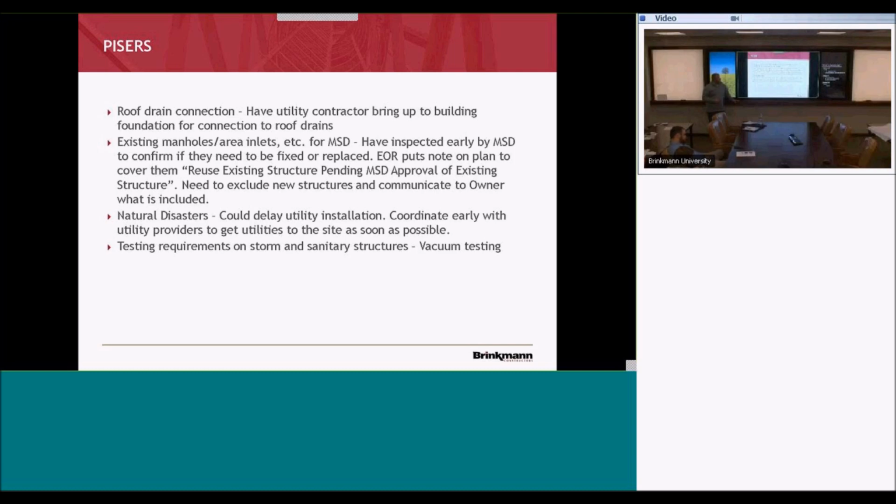Couple things on this, when working with utilities like MSD, Laclede, Ameren, normally, once you get past that design phase and there's a cost presented, they don't move without two things: whatever agreement is needed, and dollars. So make sure your owners are aware of that, because Laclede or any of them, if they don't get paid, then they're not moving forward with the project. The other thing too is if they are working on your site, they're still required to coincide with any dig right requirements too.